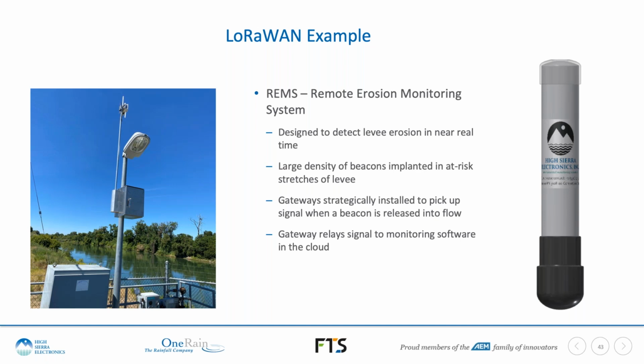But this is what we're calling REMS. It's a remote erosion monitoring system. On the left here in that cabinet up on the pole, we see the gateway is installed, and it's a levee erosion detection system. So the intent is to detect levee erosion in near real time. On the right-hand side, we see a beacon that's about 3 inches in diameter and about a foot tall. Those are installed in a levee, and there would be a fairly large density of beacons implanted in stretches of the levee that are at risk for